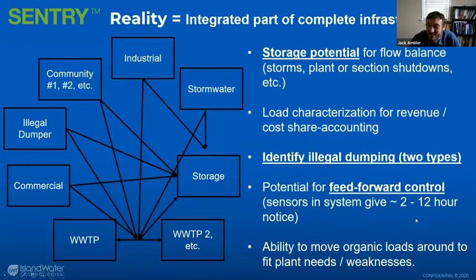Kind of a nice, interesting go forward here, and some of the Arizona plants are starting to do a bit of this, which is actually kind of like an ultimate feed forward control. So, a typical wastewater plant might have upfront sensors that might give you an hour or two's heads up before it hits your biological system, or maybe a little bit less than that.